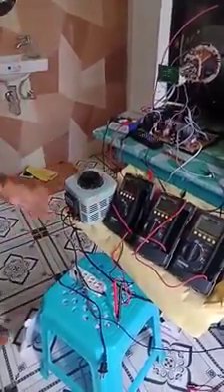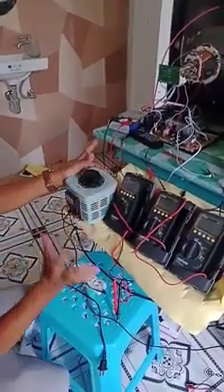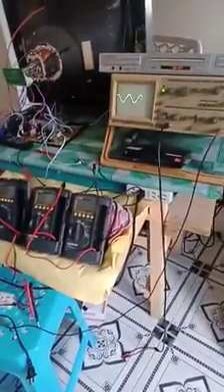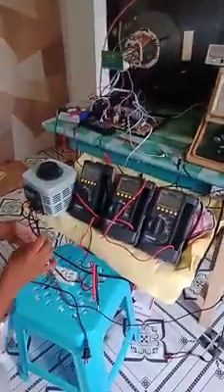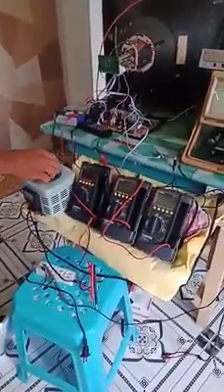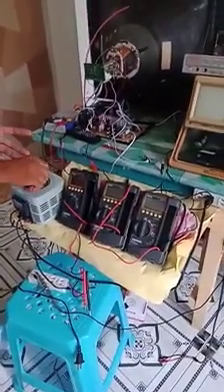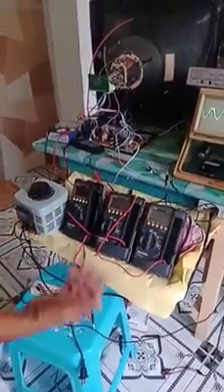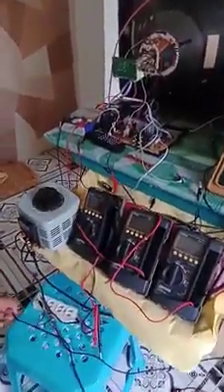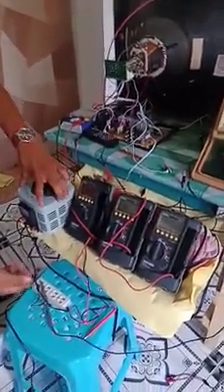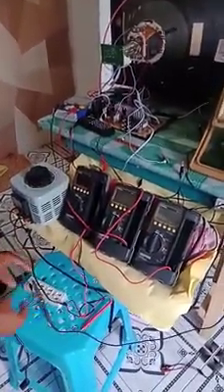Going back again to this variac transformer, what really is the operation of the variac transformer? Okay. Variac transformer actually has two windings. The primary, we have here, and the secondary winding as the output line. It is equipped with a variable, or the so-called rotor shaft, that will vary the setting of the voltages at the output. Now, actually, the primary winding is connected to the outlet that distributes 220 volts to this variac transformer, and the output now is at this outlet.